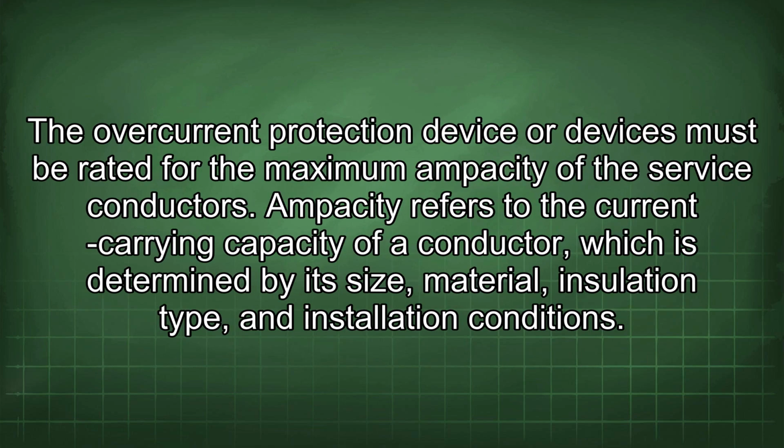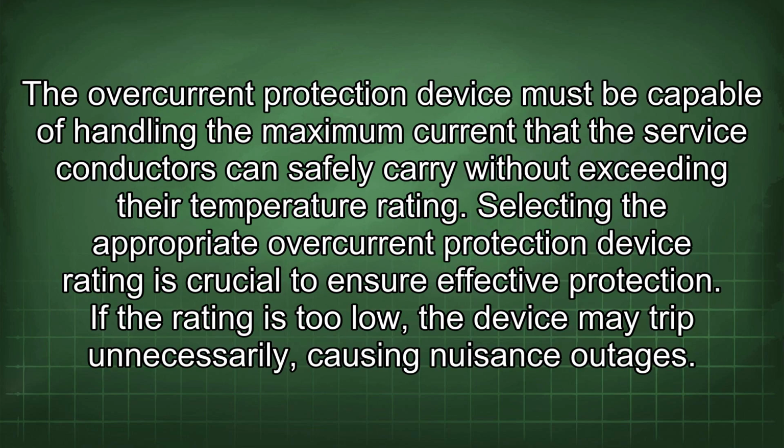The overcurrent protection device or devices must be rated for the maximum ampacity of the service conductors. Ampacity refers to the current carrying capacity of a conductor, which is determined by its size, material, insulation type, and installation conditions. The overcurrent protection device must be capable of handling the maximum current that the service conductors can safely carry without exceeding their temperature rating.